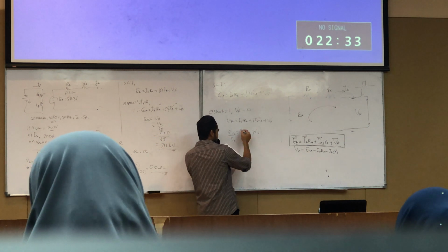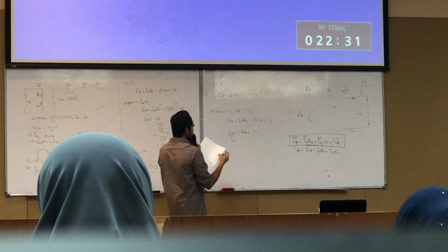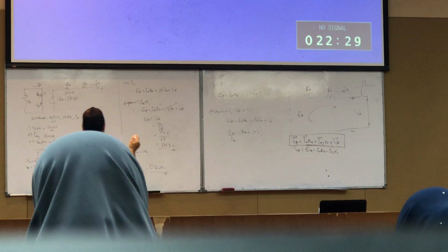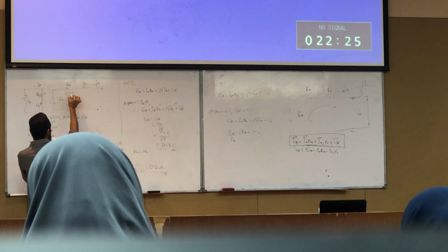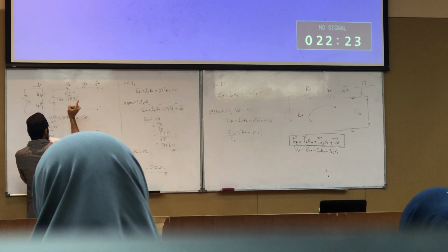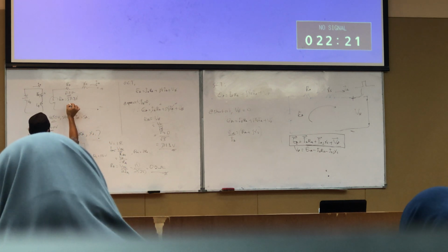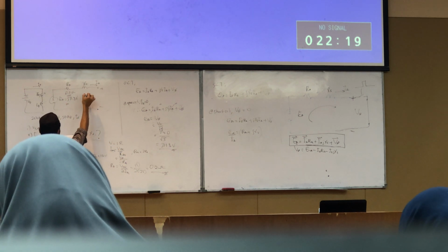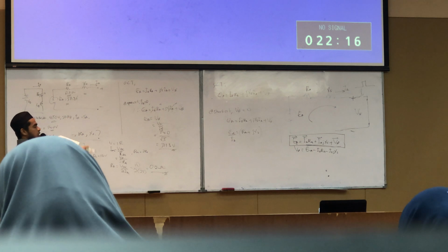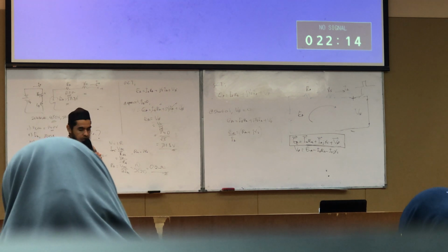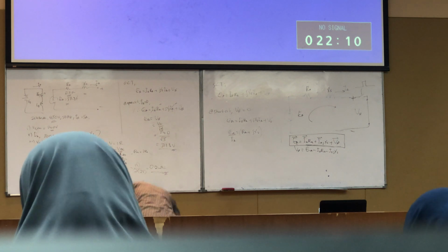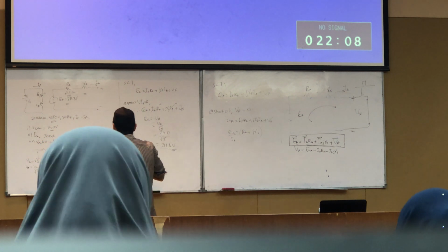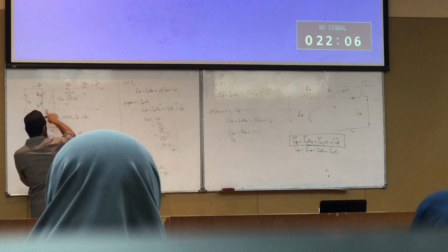You calculate, and you will get this XS. From the DC test we calculate RA. From the open circuit test we get EA, from the short circuit test we get jXS. Later we will do it. So these 3 tests produce the values that you can fill in this single phase diagram.